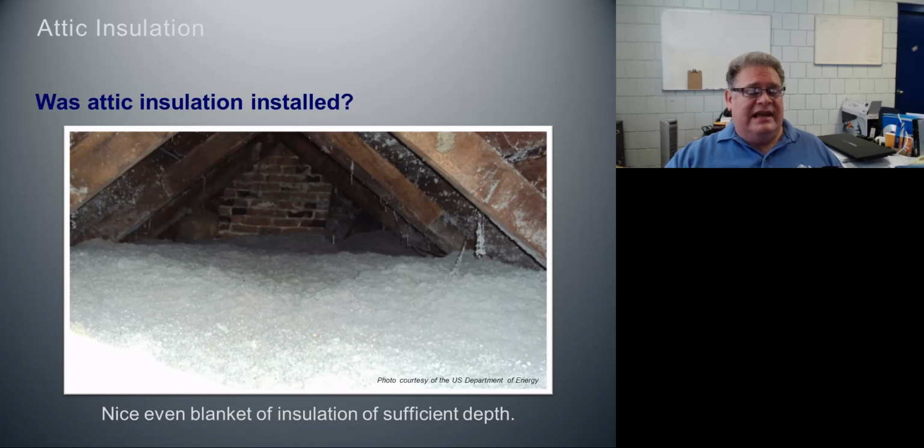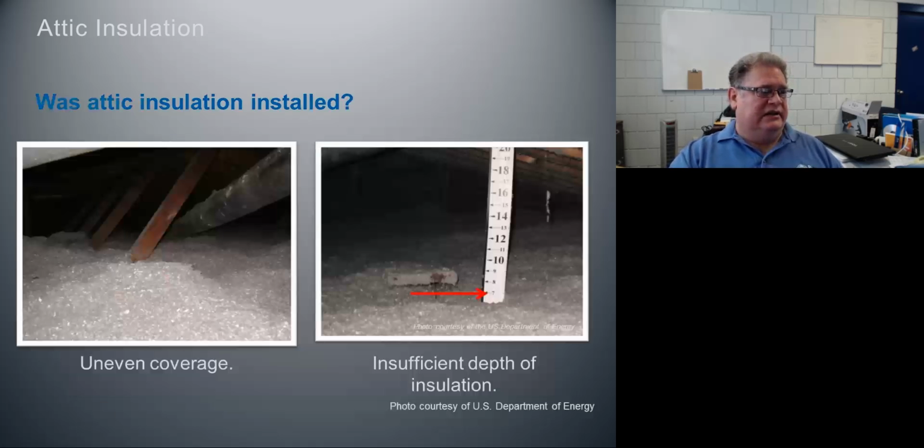Okay, depth is not your only indicator. In other words, how deep this insulation is not as important as knowing your bag count and a good measurement of the attic floor. Because the manufacturer gives us a specification of how many square feet maximum that we can cover of an attic floor with a bag before we're mixing too much air with it, and we're going to get heavier settling than we want, which means we're not going to wind up with R40, we're going to wind up with something else. So don't use depth as your only guide.